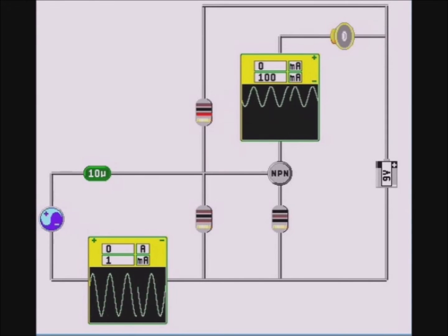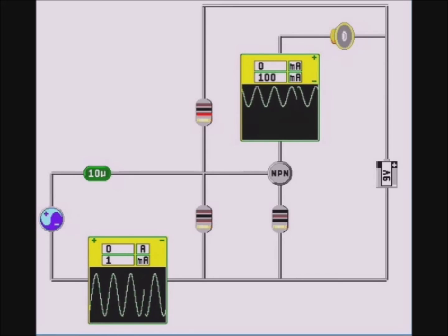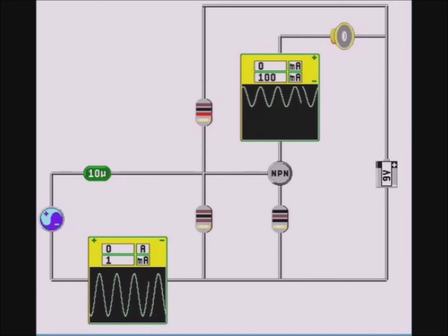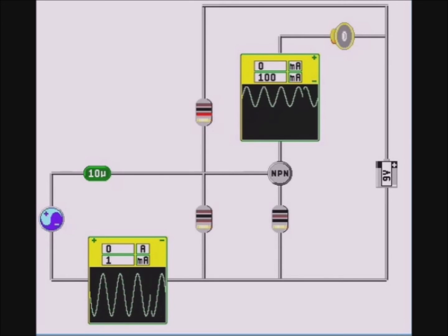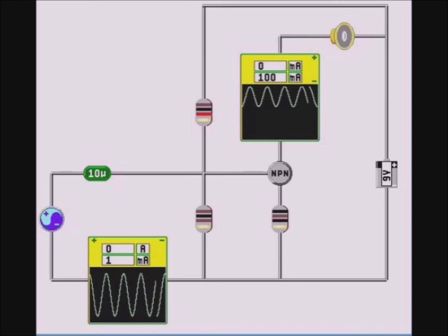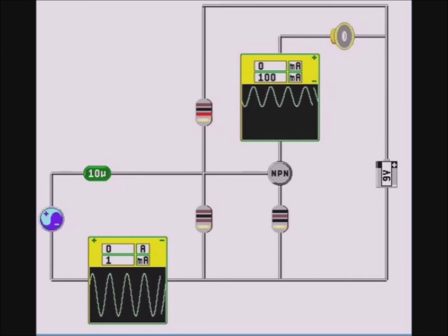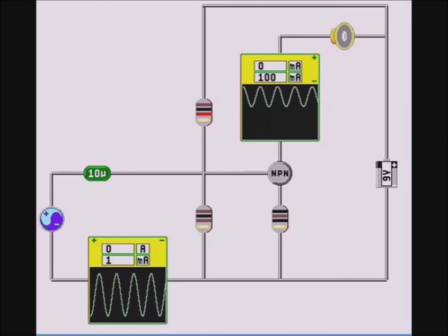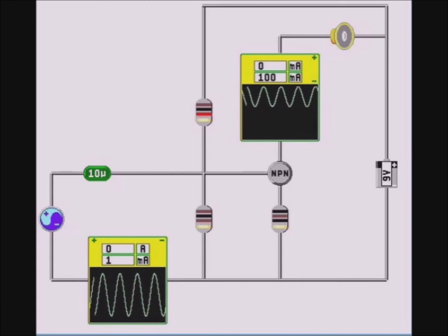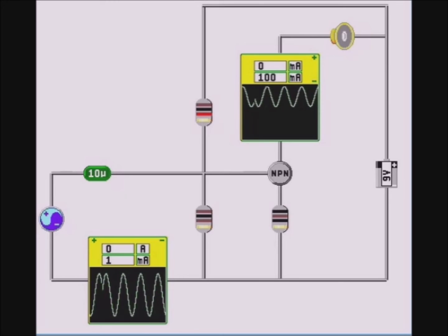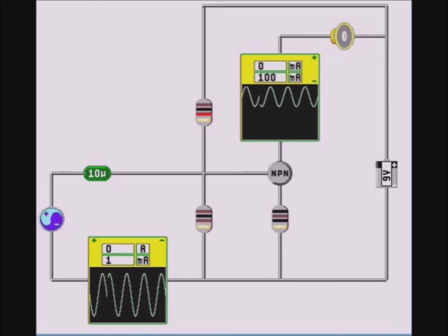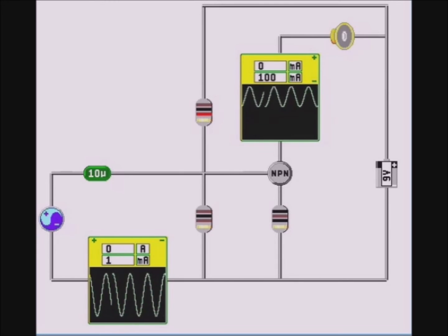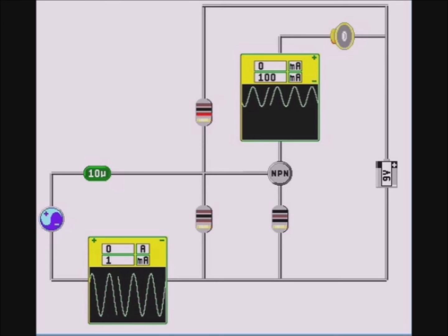In that example, the current was sufficient to drive the speaker. But what if the current were too small for the speaker to play an audible sound? Here the wave generator is producing a 440 Hz wave with voltage amplitude of 50 millivolts. Passing a current from this voltage through an 8-ohm speaker is not sufficient to make the speaker sound. So we create a simplified amplifier.